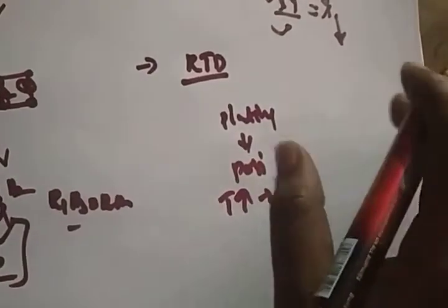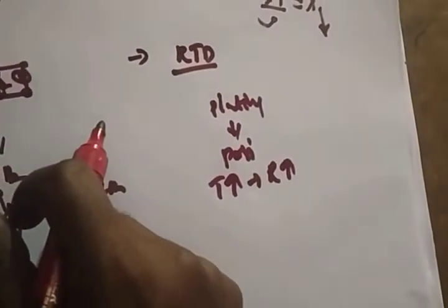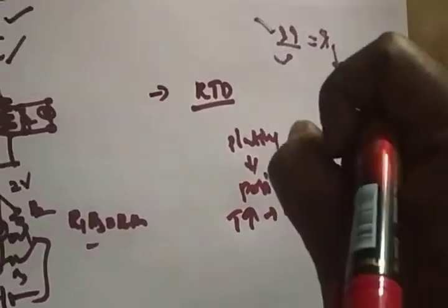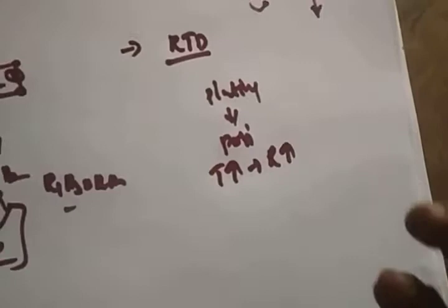There are also semiconductor materials with a negative temperature coefficient, but we need not go for this one. If the resistance is reduced, you can get a difficulty while finding the changing resistance, right? So that's why you always prefer platinum or other conducting metals for finding the temperature itself. How will it work? Whenever temperature is applied to that metal, the metal resistance will change.